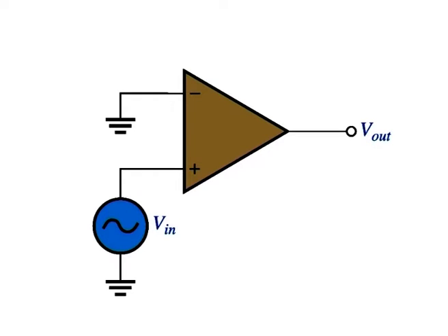Because an op-amp without negative feedback is essentially a comparator, we will look at the comparison function using a typical op-amp. Zero level detection. One application of an op-amp used as a comparator is to determine when an input voltage exceeds a certain level. Figure here shows a zero level detector.